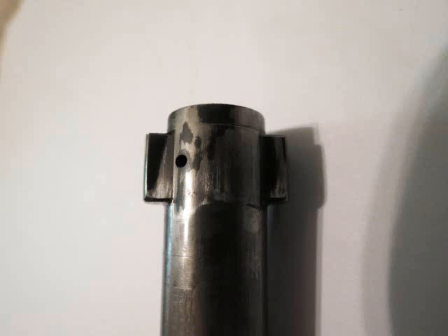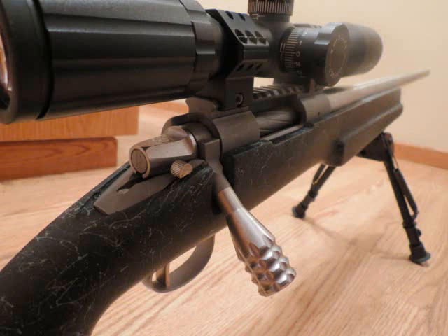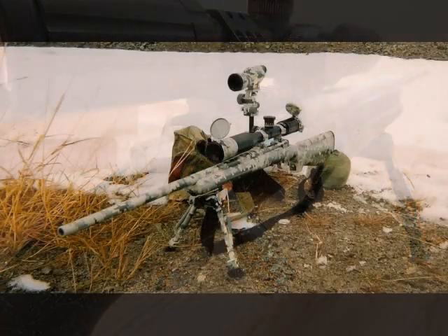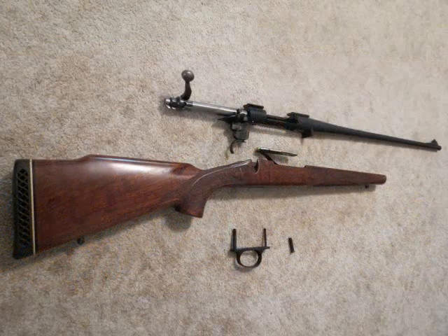What a lot of guys do, if they get a bolt-action rifle and want to have it accurized by a gunsmith, is they'll take it in and have the bolt lugs lapped. They basically put an abrasive compound on those lugs, like a rouge type stuff, and put it in there under spring tension so that it's pressing backwards against where the lug surfaces are, and they'll work that bolt back and forth, and it just smooths down the two surfaces so that they're perfectly mated against each other.